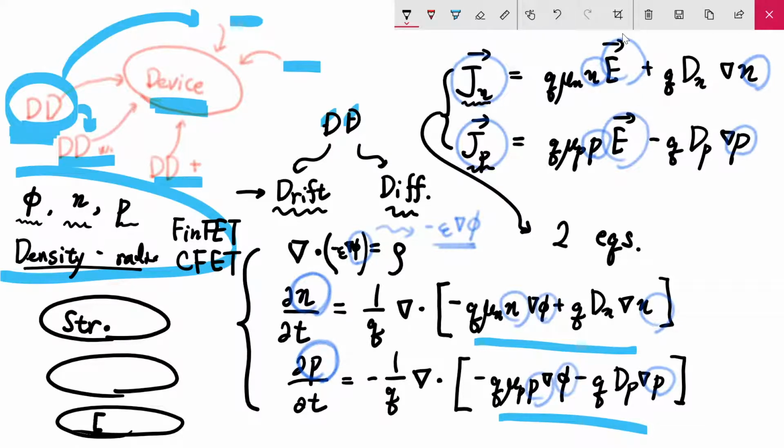Also, now we are talking about equations. Your equations can be fully set by the users. Maybe I just want to solve the simple nonlinear Poisson equation, or the standard drift-diffusion model, or sometimes I can spend more computational resources and solve one additional equation for this system. That should be available to the users. So you as a developer should allow the freedom to choose the set of equations to users. Therefore, the structure can be loaded from an external file, the equations can be set by the users, and here you have your own implementation.